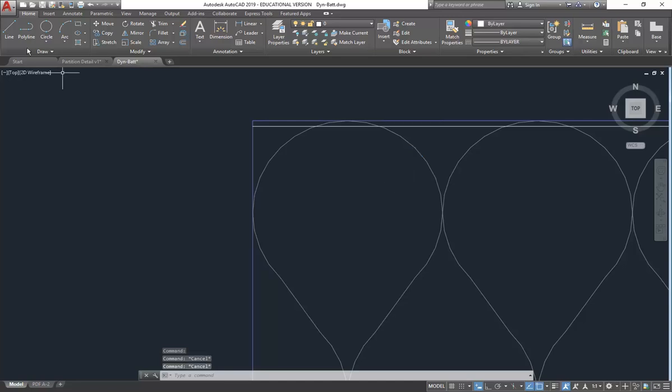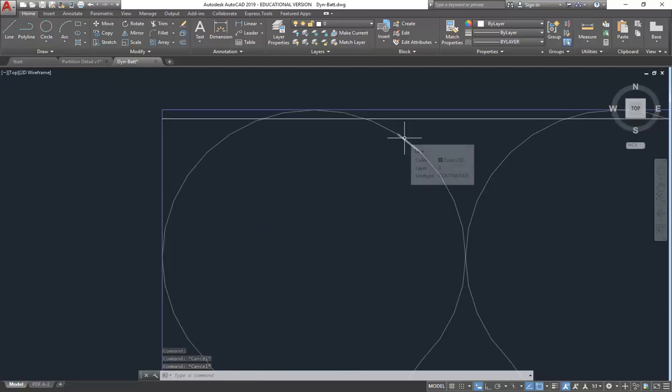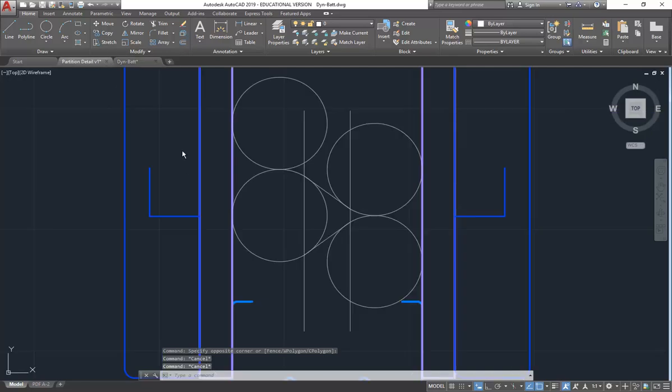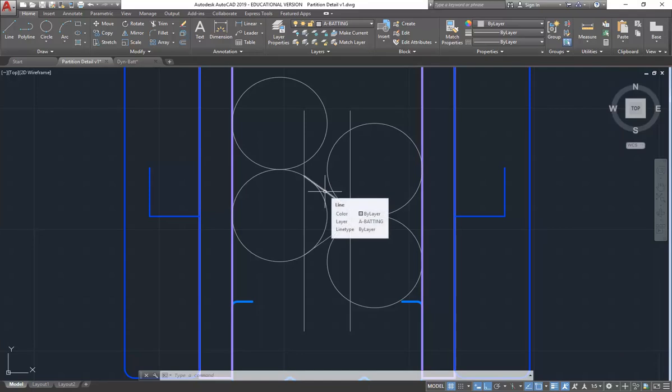Splines are great, but when you convert splines into polylines, they give you all these extra points, and that's hard to work with. I think it's easier if you can keep it as a simple curve. So I've got my two lines, which also will give me a thing that I can use to trim my circle. So that's the next step.